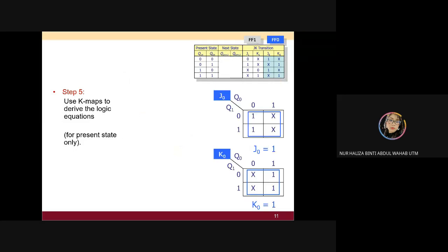So here, you have the Q1, Q0 here, and it doesn't matter if you change this place. But your answer here should be similar in terms of mapping. Okay, I did the Q0, Q1. Q0, Q1: 0, 0, 1, 1. Like this you can see, I changed the place. If 0, 0, you can see here, 0, 0, I have my J0 as 1. Yeah, and that is correct.